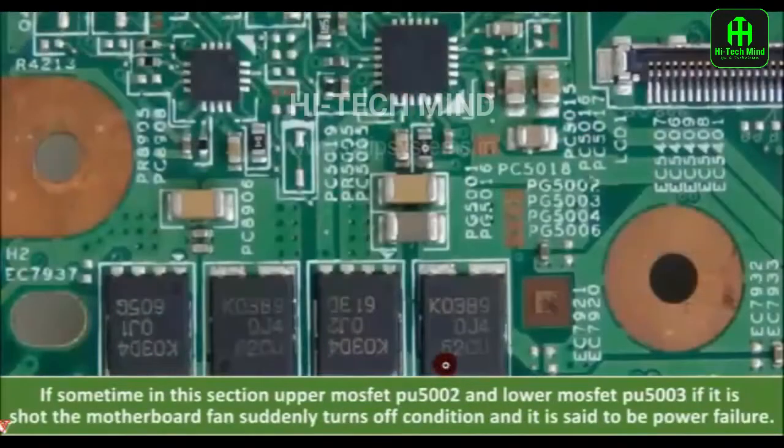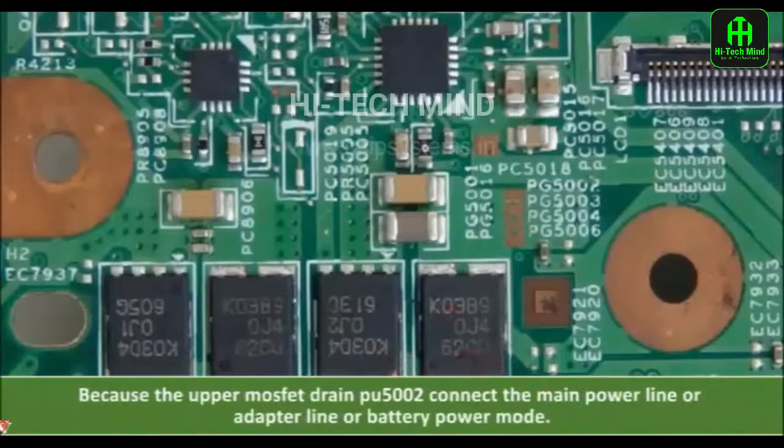Sometimes in this section, if the upper MOSFET PU5002 or the lower MOSFET PU5003 is short, the motherboard fan suddenly turns off, and it is said to be a power failure condition, because the upper MOSFET drain PU5002 connects to the main power, the main power line, or adapter line or battery power mode.